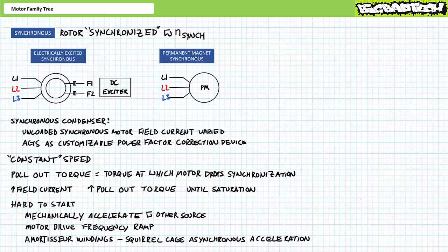Lastly, synchronous motors often necessitate more complicated starting circuits and protection schemes than would a similarly rated induction motor. One of the principal issues related to starting a synchronous motor is that upon closure of a full voltage starter, the stator rotating magnetic field is instantly established at full speed, whereas the rotor with applied load with some level of static inertia may take some time to come up to this speed.